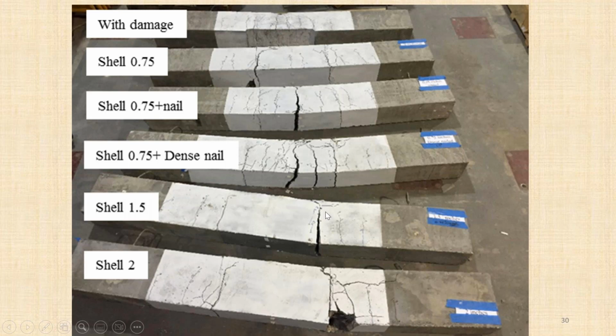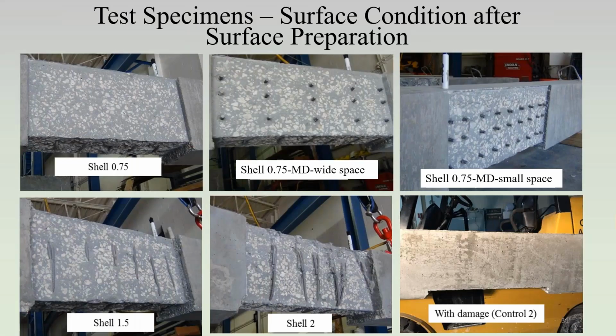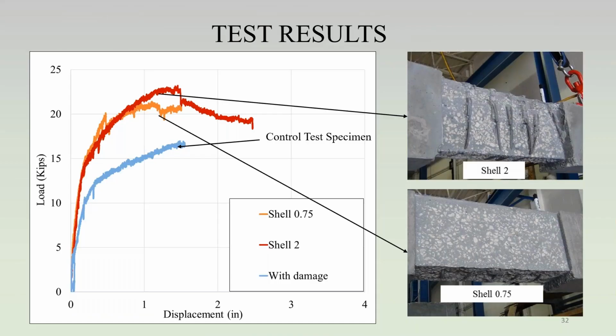And I'm going to elaborate on the idea of the plastic hinge that John mentioned and what the solution could be. But here, certainly anywhere you use UHPC, expect that the damage is going to shift from there to somewhere else. And of course, the strength really increases significantly too.